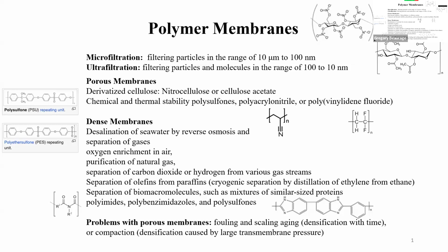And they don't see the other gas atoms because the size of the pore is so small, it basically acts like a dilute gas at that point. But the pore drag. So anyway, the transport drops, but the dependence of the transport on the size of the pores changes dramatically when you go from diffusion to this kind of Knudsen transport, right?